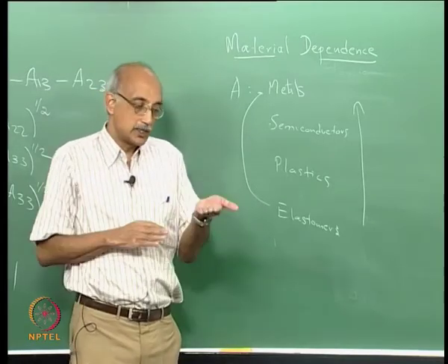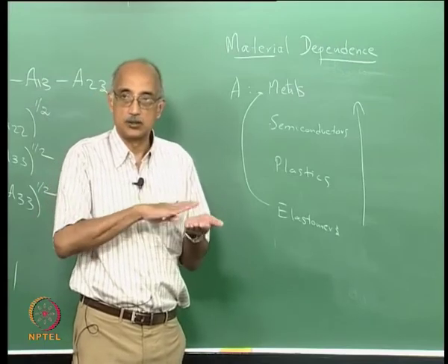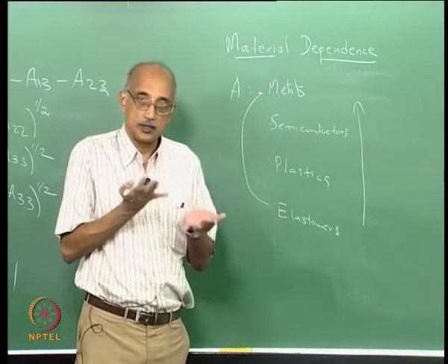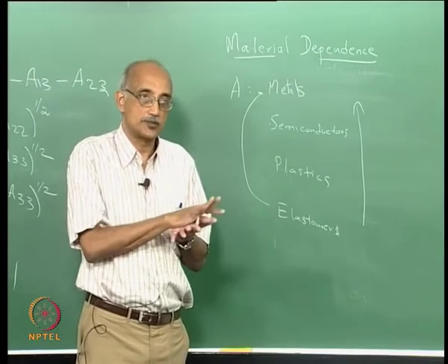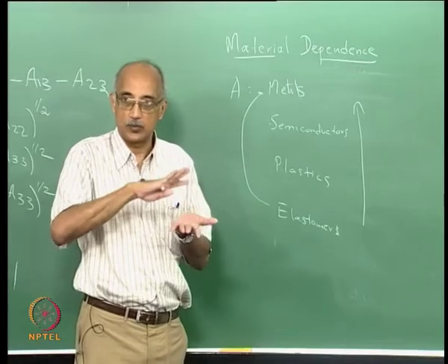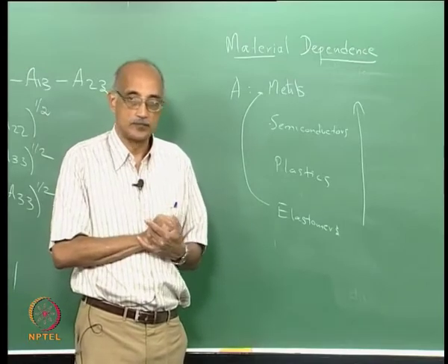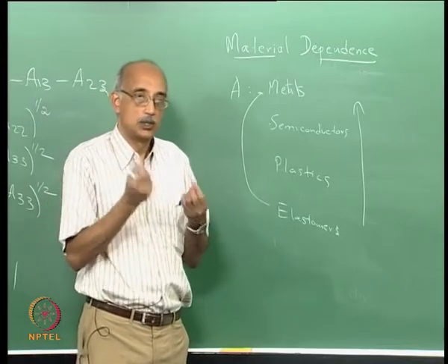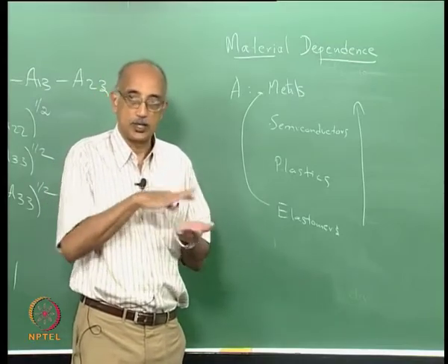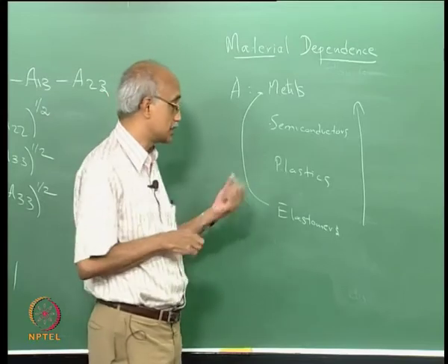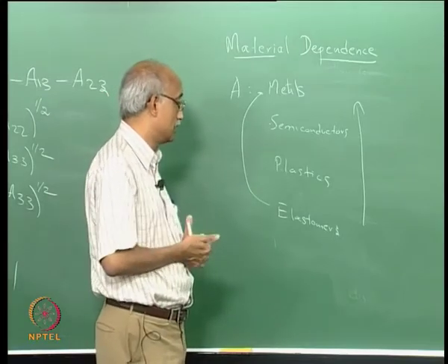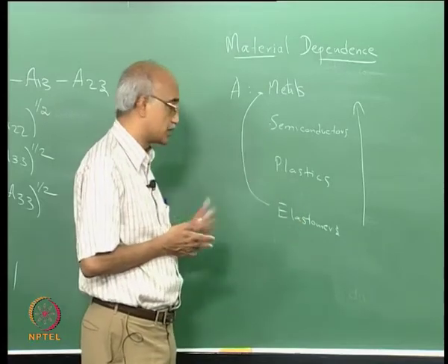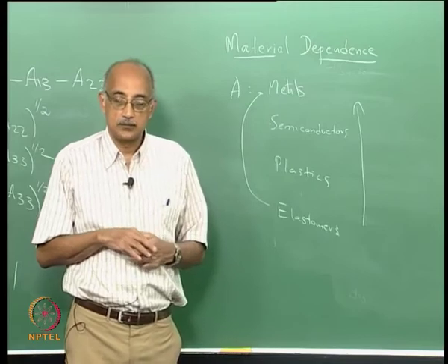However, if you are taking a silicon surface and you want to polish it using silicon oxide abrasive, that is not so good, because there is going to be a repulsion. So, the silicon oxide particles may find it difficult to make contact and provide good polishing for the silicon surface. So, you may need to use again additives to improve the contact between the polishing abrasive and the surface that you are trying to polish. So, there are a lot of interesting implications of this type of behavior that we need to be aware of.